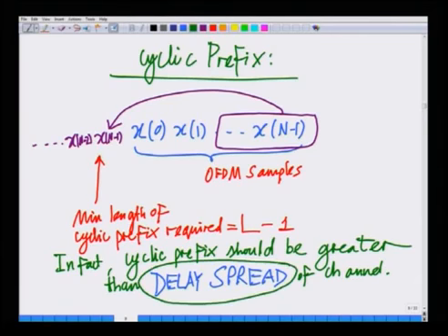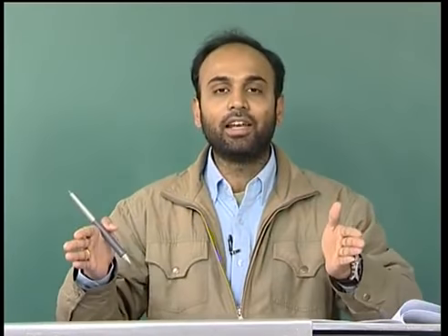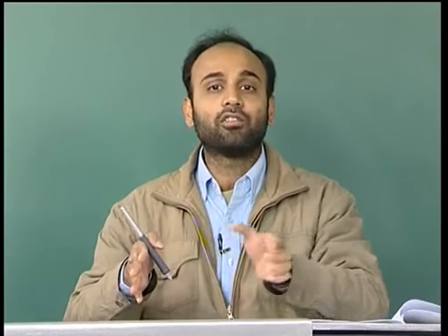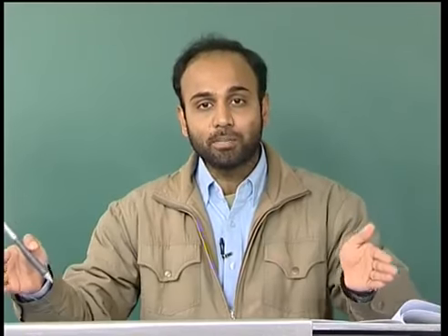This is key. Remember, we said in a wireless communication system the channel has a delay spread, that is, energy is not arriving at a single point of time, but it is arriving with a delay. That is what gives rise to this intersymbol interference and this FIR filter of channel taps of delay spread L, because signal energy is arriving across the spread.